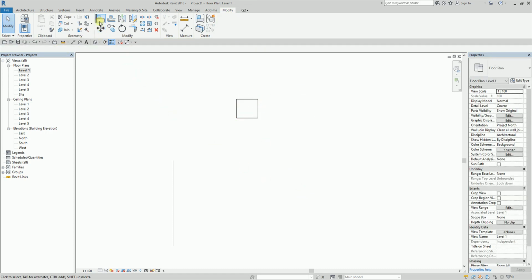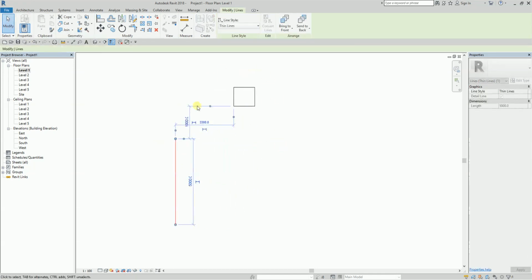If you are now going to align that, select align, select the reference, and then this one. There you go. You also have an option here to lock your aligned object to your reference line here. Meaning to say, if you lock it and try to move this line away, your aligned element will follow as well. So first I'm not going to lock it. Just to show you, I'm going to select modify. If I drag this, you notice it's not following, right?